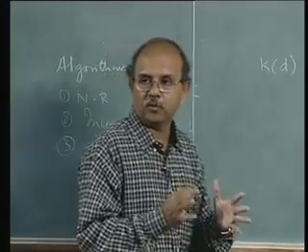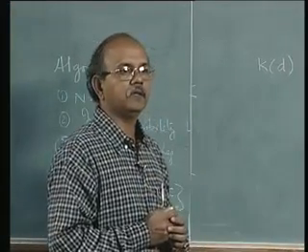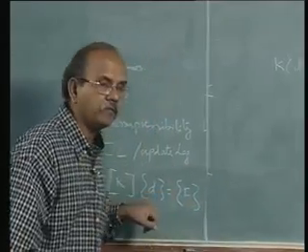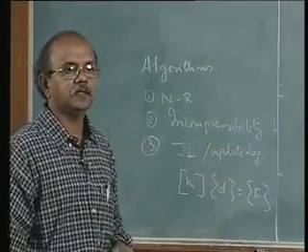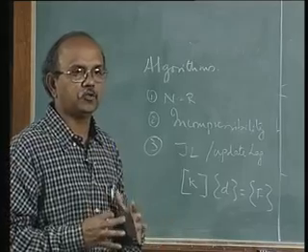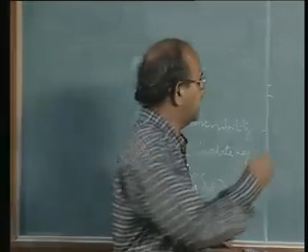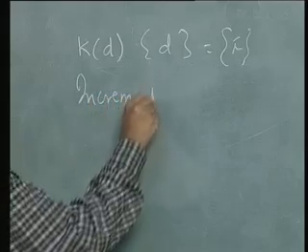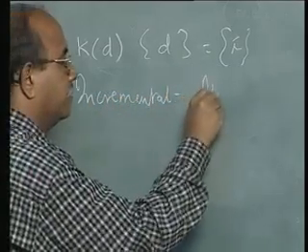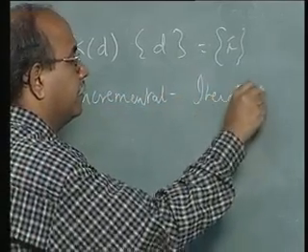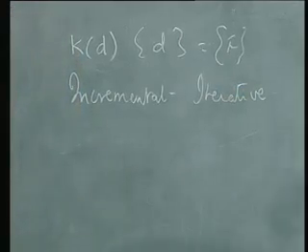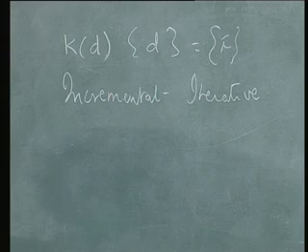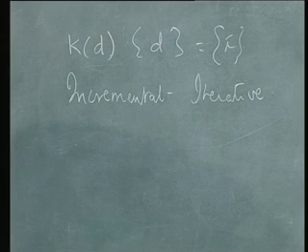Let's first look at the procedure. The major difference between a linear problem and a nonlinear problem is that we are going to resort to an incremental iterative approach for solving these nonlinear problems.